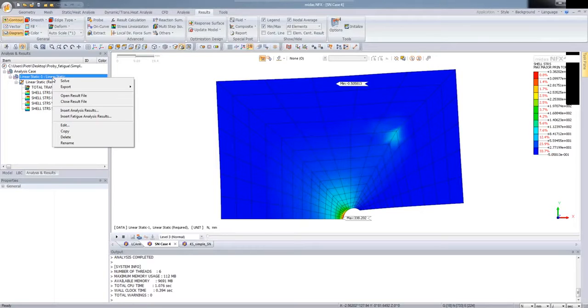And every time before we start doing these calculations, we have to make some decisions related with the process. For example, for the stress life, we're supposed to investigate the loading type, mean stress effects, multi-axial stress correction, and for example, the fatigue modification factor, which is also known as fatigue concentration factor. So these are some points which are related with the stress life method. And in this example, let's enter the fatigue module.